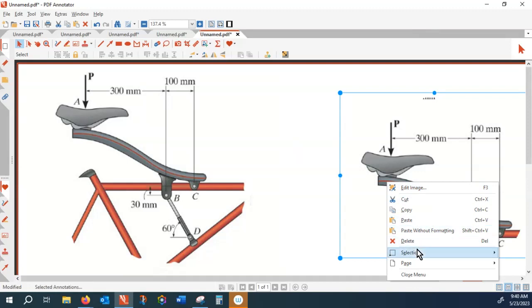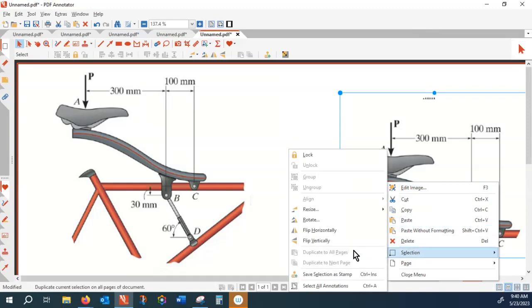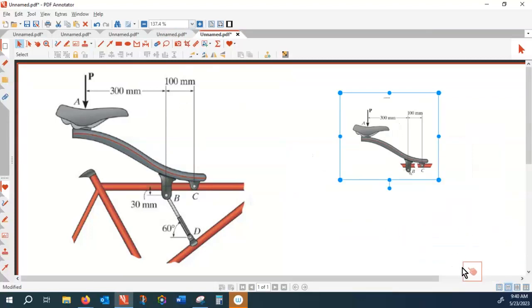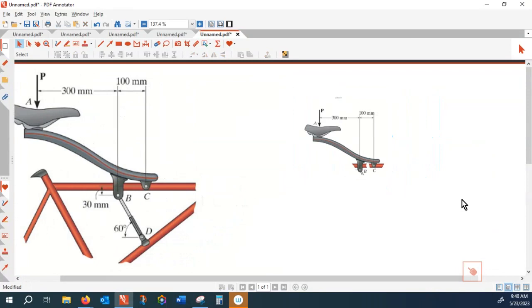So now my free body diagram would look like this one. Okay, this is an external force. The weight is ignored, and that one is a compressive force, which I'm going to resolve into two components because that is with a 60-degree with the horizon, right?